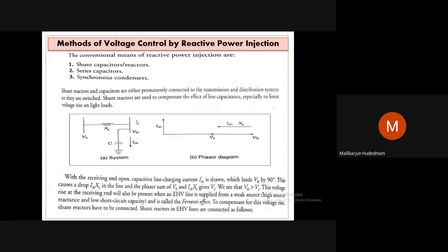That means if the system is highly inductive, to compensate that, if I incorporate a capacitive reactance or capacitor at the optimal point, let's say at the bus itself, marked as a capacitor inserted, it will definitely create leading volt amperes. Hence, you can see the receiving end voltage VR and the sending end voltage Vs, and the current flowing through this installed capacitor.